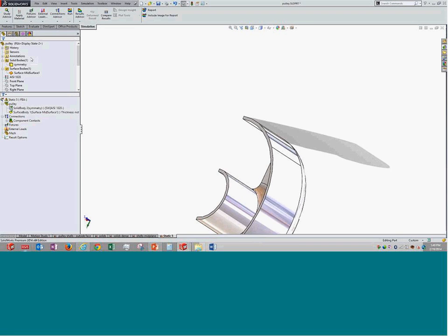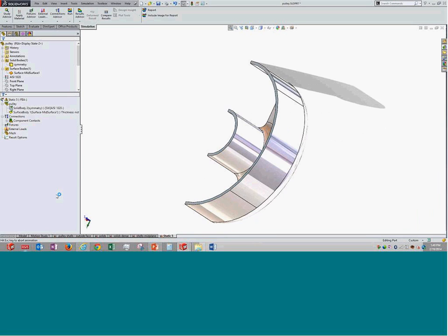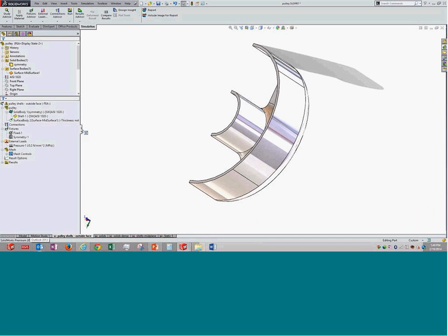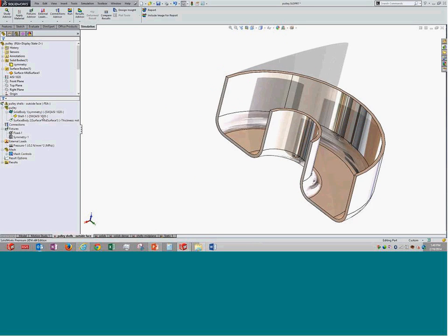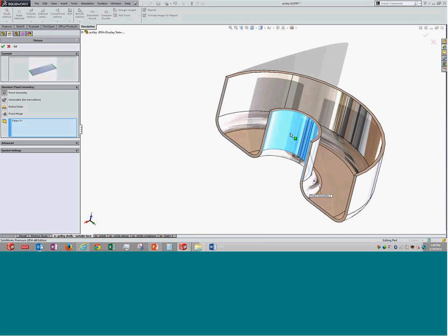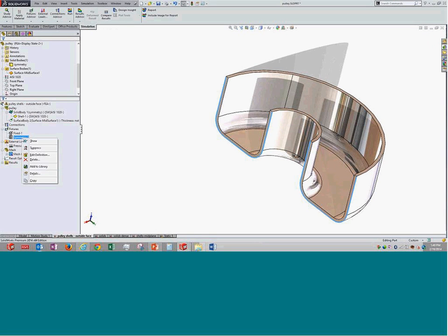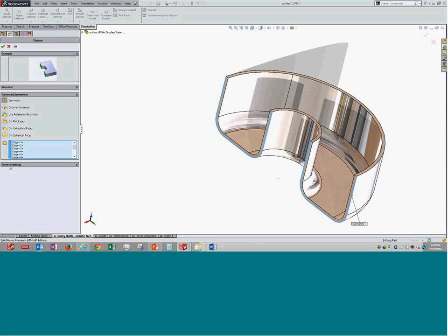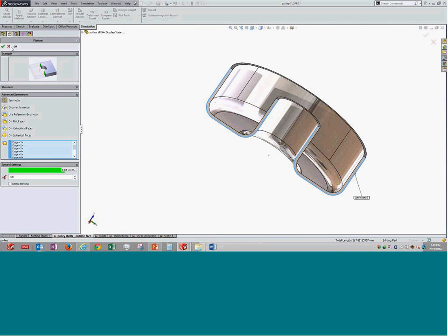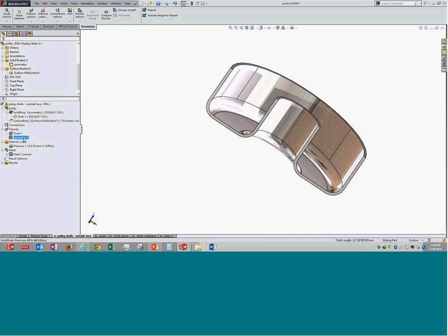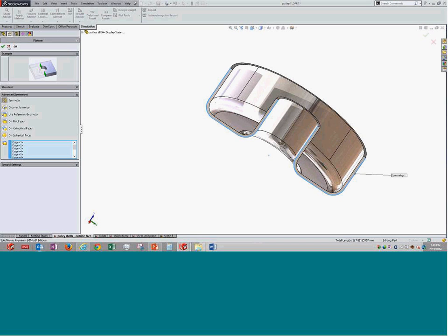Goals have been already created here. You can see the setups. The method that I mentioned has been used. It is already defined over here. The central surface is fixed, and certain conditions are used. By the way, this is another point we will discuss a little bit later, but this is a half cylinder, so we are using symmetry conditions over there. Let me check. It's fine. Finally, pressure. Okay.